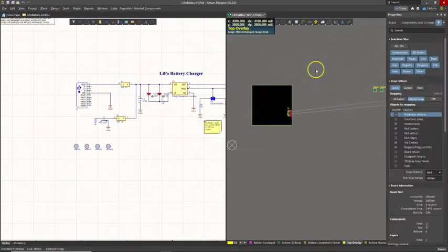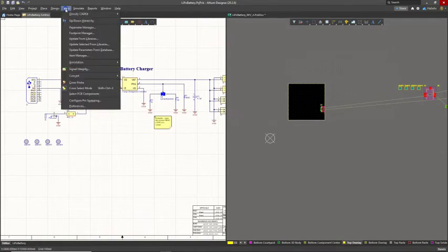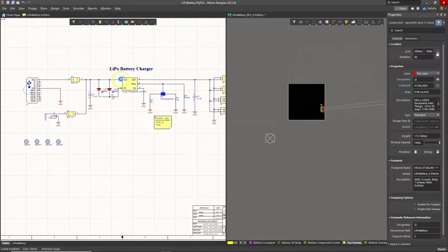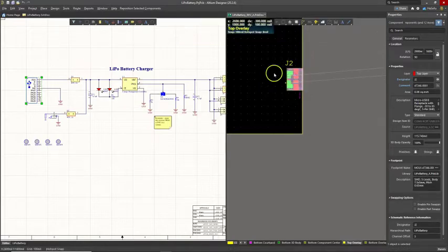So then what happens is when we select a component, as long as we're in Cross Select mode, Tools, Cross Select mode, when we select a component, it gets picked up automatically on the PCB and we reposition selected components. So I'm going to click and place it there.